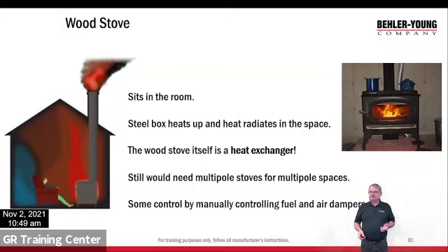multiple rooms. Control, well, we talked earlier about combustion, right? If I reduce air, I reduce combustion. So I can cut down the air, primary air. I can cut down the flue vent speed. I can slow down the combustion. All right, it's all contained inside. You can see it's a yellow flame, so there's all kinds of nasty flue gases coming off that, but we're putting out that.